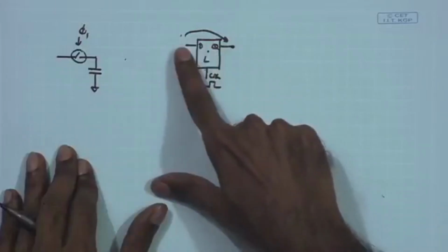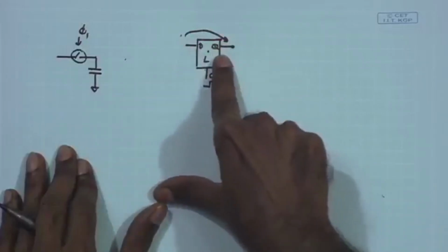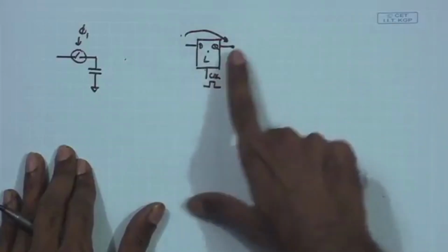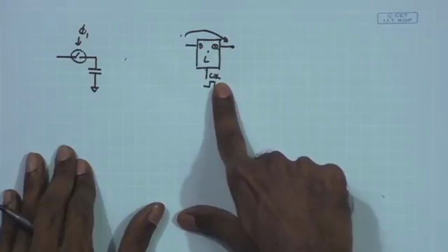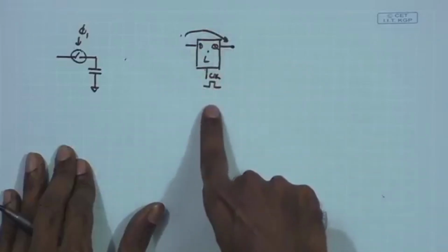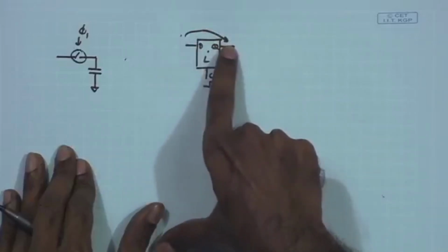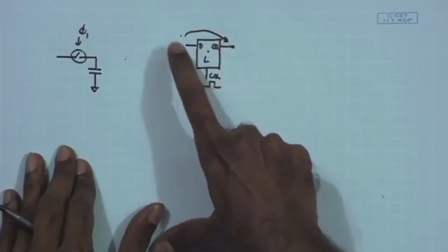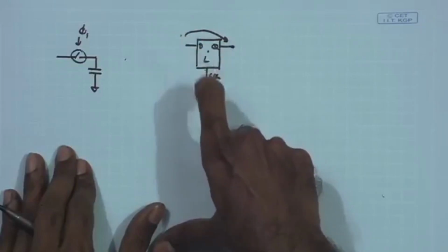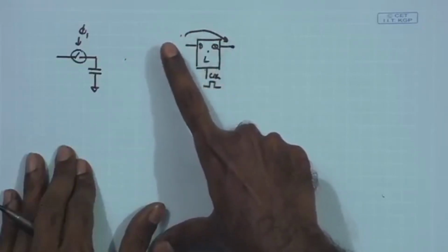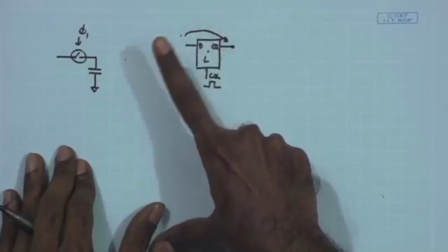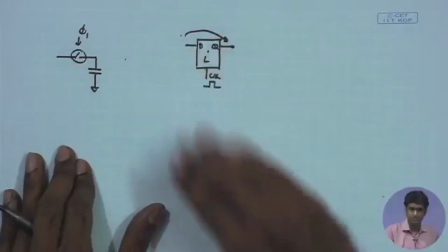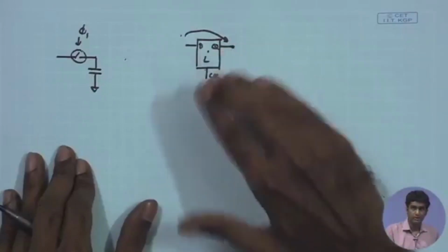It is sampling the digital bit and storing it when the clock level is low, and the negative level sensitive latch does the same thing when the clock is low. So, it samples the digital data when the clock level is low, and it is transparent during that phase, it is tracking the data. So, if during the low phase of the clock the data changes, the output will also change. That is the negative level sensitive latch, and when the clock goes high, again it becomes opaque and the data over here is supposed to be stored.